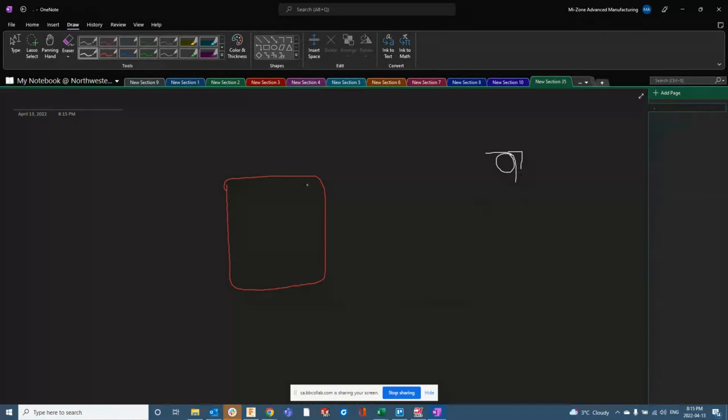There's no way, right? So if I give you this drawing and I call it a radius of 0.25, I told you to use the largest tool diameter possible. And this is just me testing you on whether or not you know what max tool diameter you can use. When you're doing a square pocket, the max tool diameter you can use is simply equal to 2 times the radius.